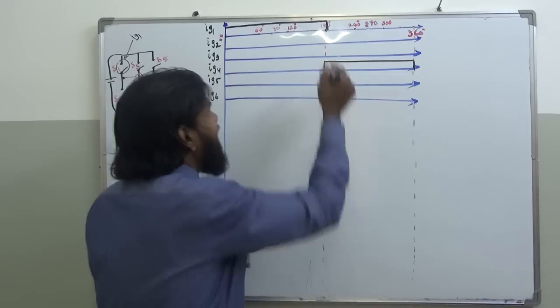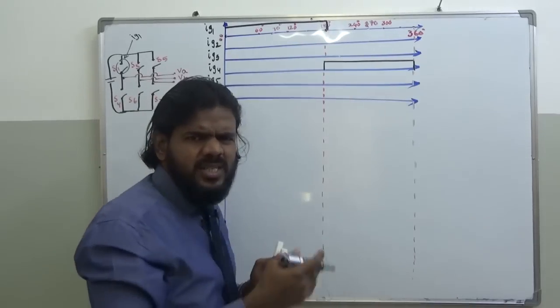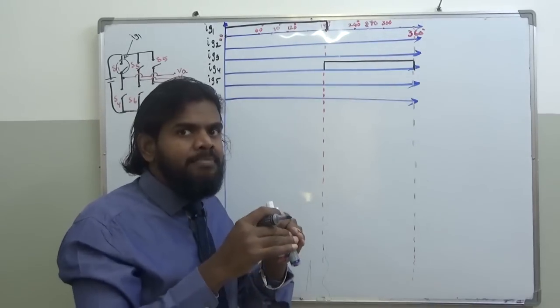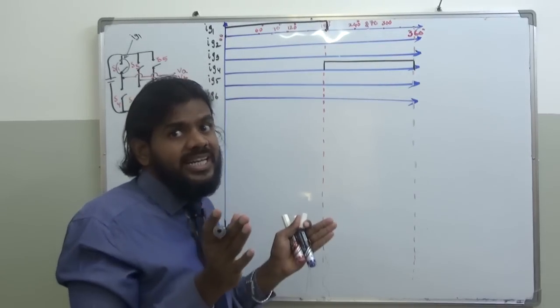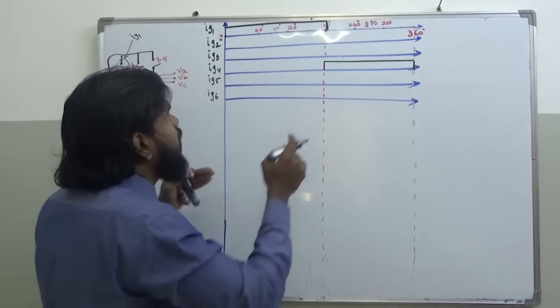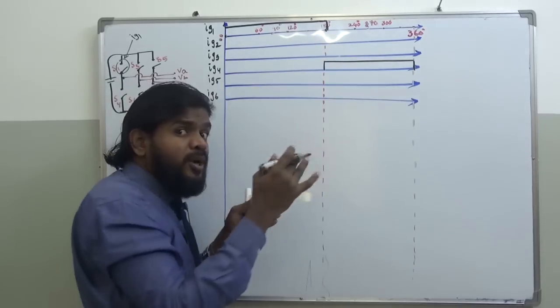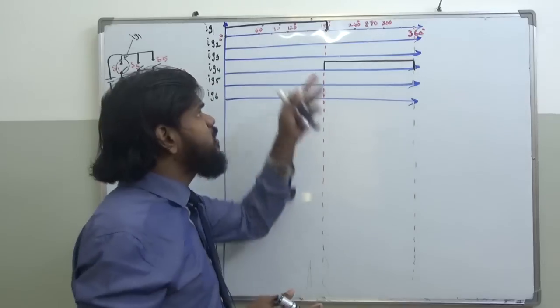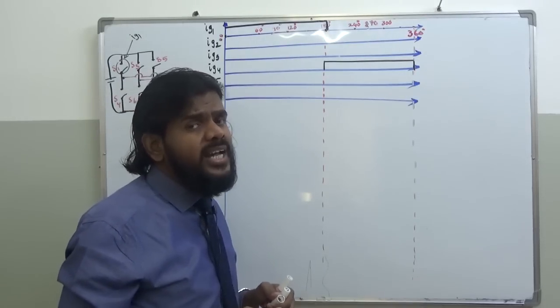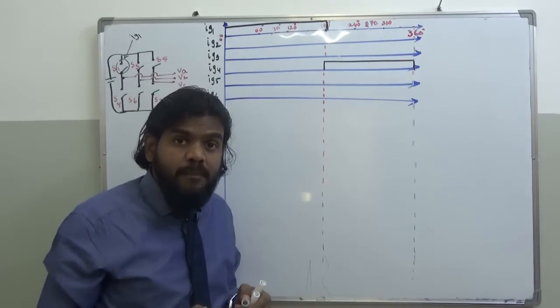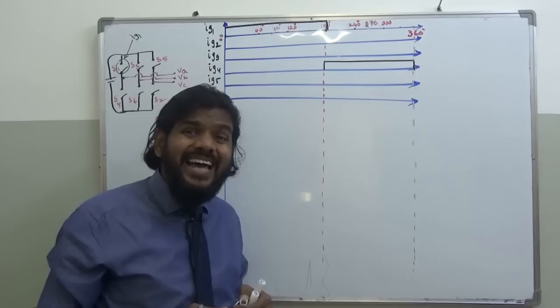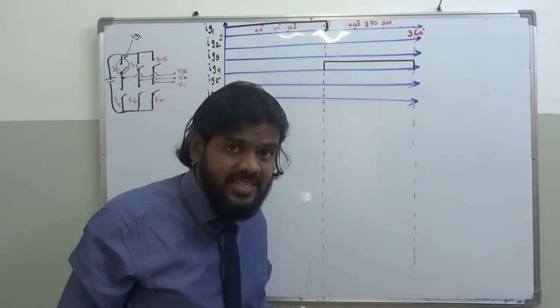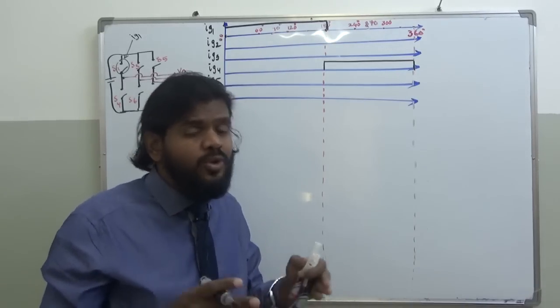And at 180, I'm making it 0 amperes or 0 milliamperes so that the transistor opens, it gets switched off. So when it is off, then your positive half cycle of phase A ends. Okay, this is the idea, right? So why will I switch off the base current there at 180? Because I wanted to make my phase A's positive half cycle end at 180 degrees.